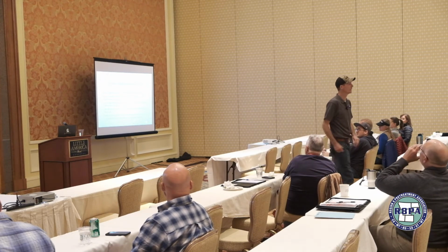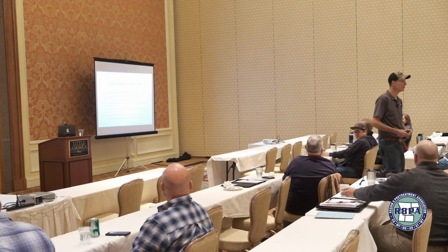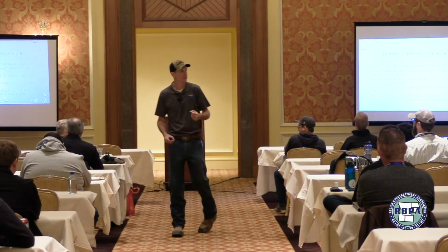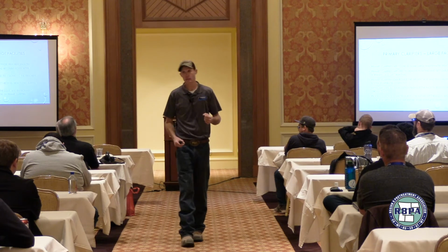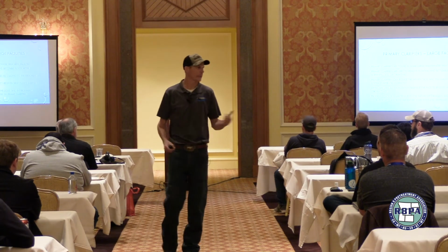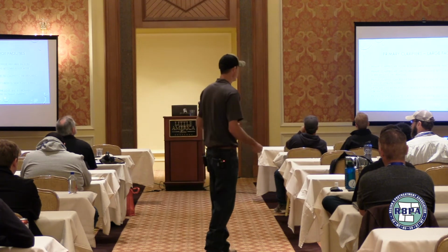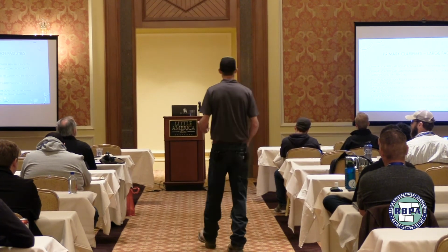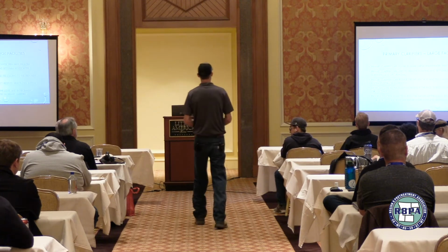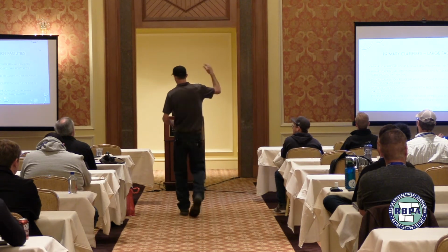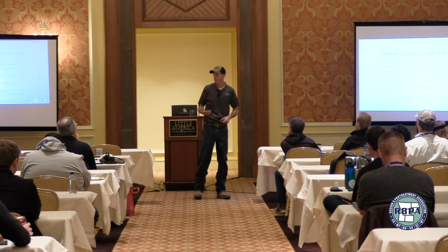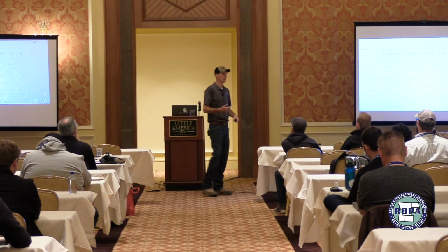In the event that I have an industrial load come through and the pre-treatment people are like, yeah, we got them. What happens to my EQ tank? It's still in there. For how long? Based on your MCRT or detention time? We don't know. So EQ tanks are a huge, huge benefit for a city or a town that has very weird diurnal flows. But from a pre-treatment perspective, they can be a nightmare.